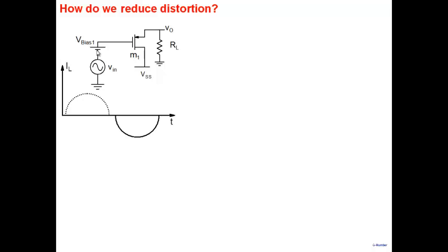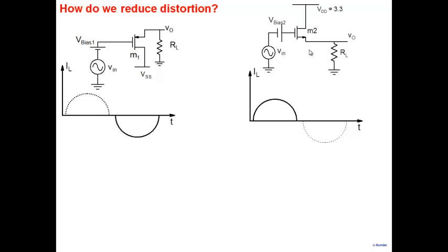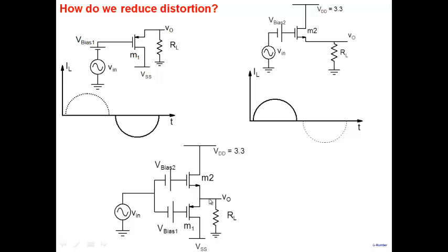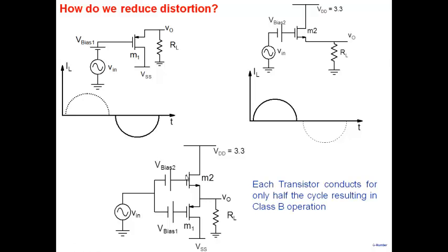Now what I can do is, using my bias voltage, I can bias it very close to threshold. And then this dead zone will not have to be there. It will immediately start conducting in the negative cycle here. So just for the sake of generality, I've kept the bias voltage here. So this gives me the positive cycle, this gives me the negative cycle, combine both of them together, and this will give me a positive and a negative cycle here.